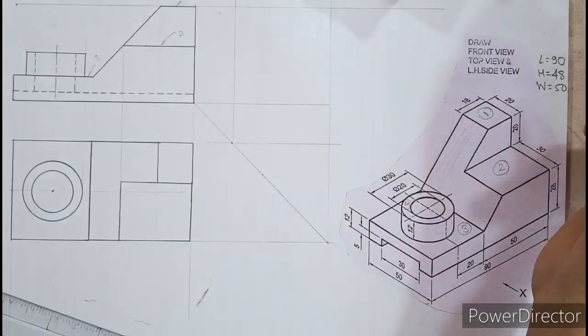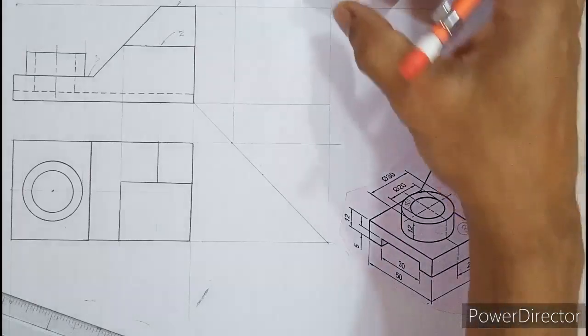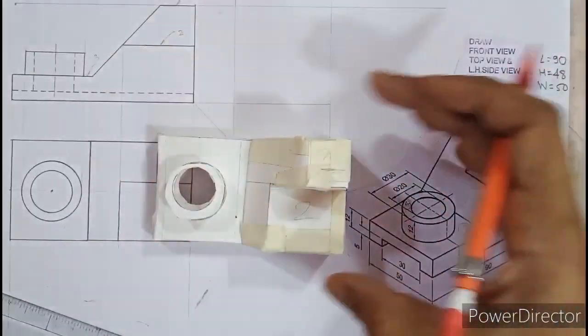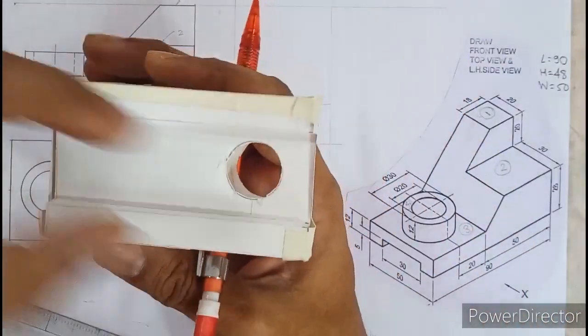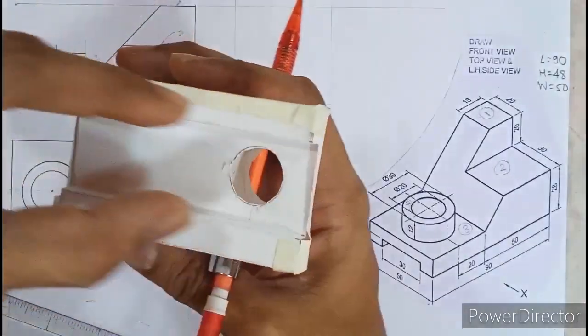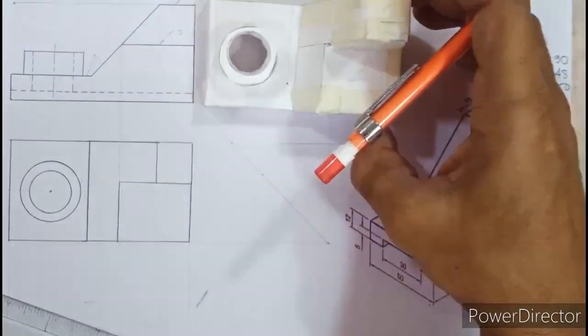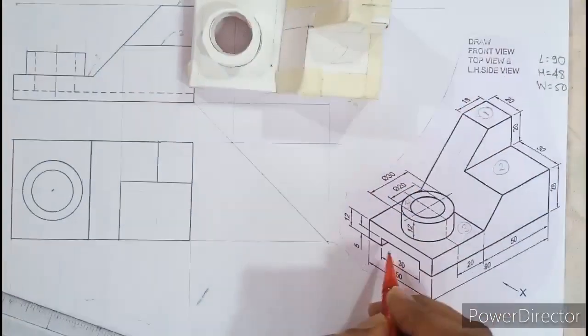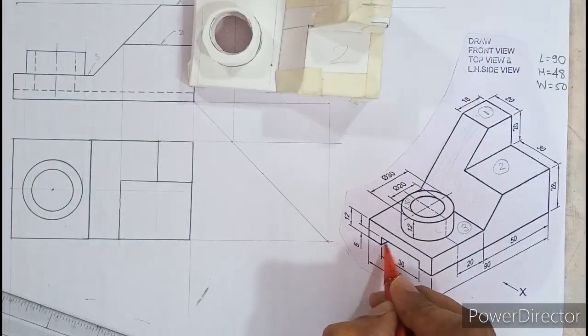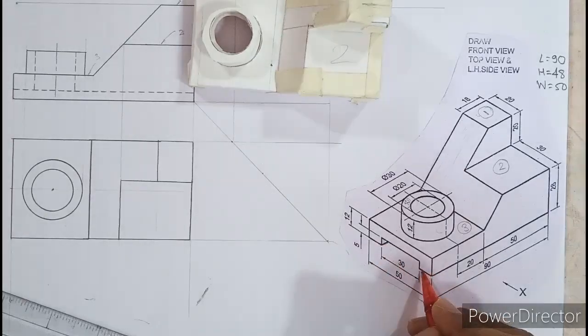The only one important thing left is when you look in the top view, you cannot see the slot running down. See, there's a slot which is being cut. That cannot be seen from top view. It means in the top view, this edge which is going inside, first and second over here, both these edges cannot be seen. Have you noticed one thing?